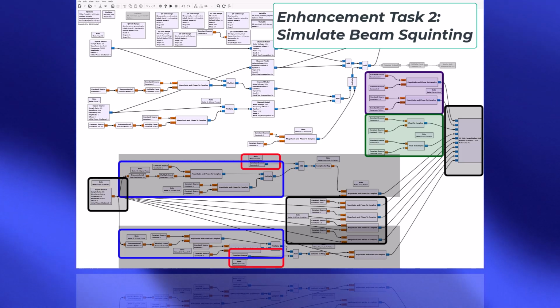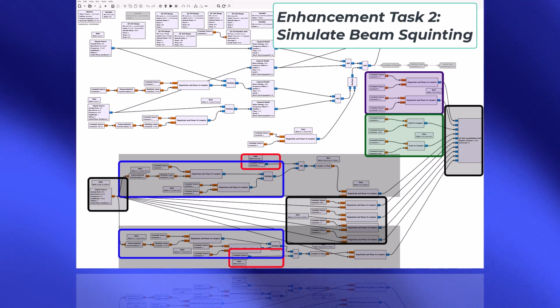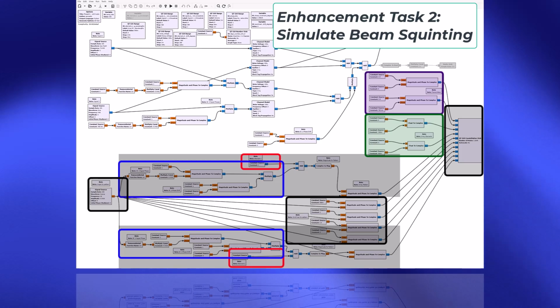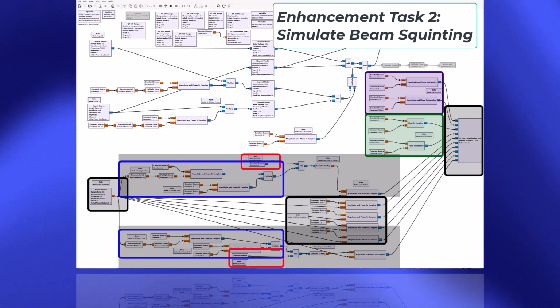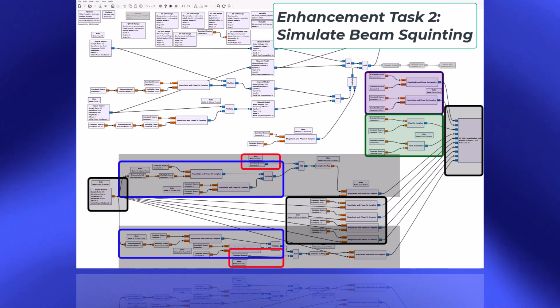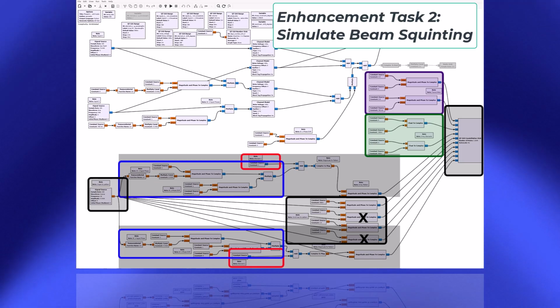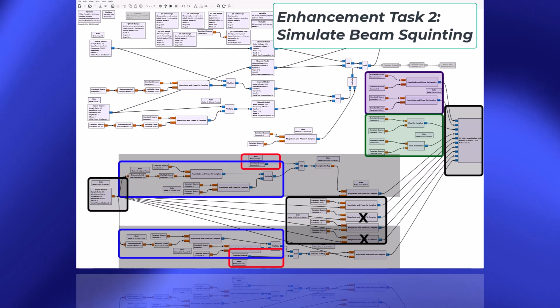So as you see, we have 4 of these grid lines, and that's taking up 4 inputs to the QT GUI constellation plot. It would be nice to have all 4, but if we need to add something else to the plot, these are the most expendable inputs. So I would just use 2 of the grid lines rather than 4. It's easy to disable or remove them. You can also go into the constellation block and make changes as needed.